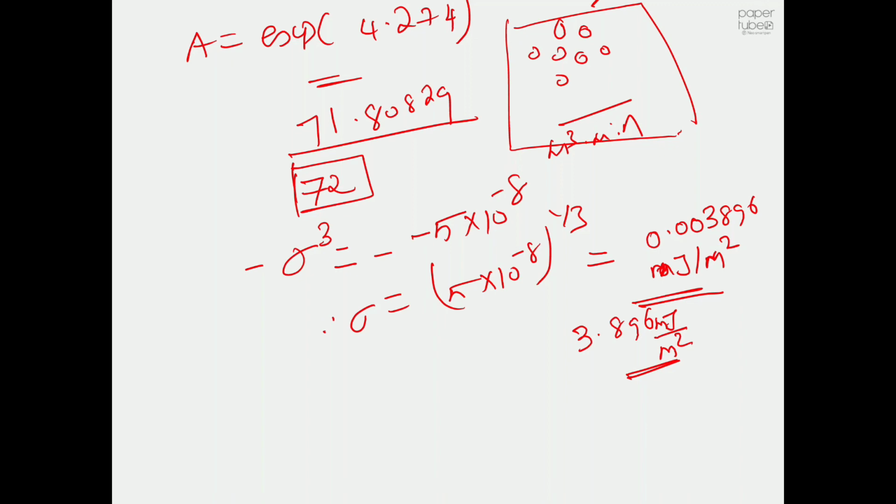And then we even calculated the pre-exponential factor. The pre-exponential factor has the same unit as your nucleation rate, so something like numbers per meter cube per unit time. In this case it is per second, as we express the time in seconds. So if you want, we can even calculate the delta G critical.